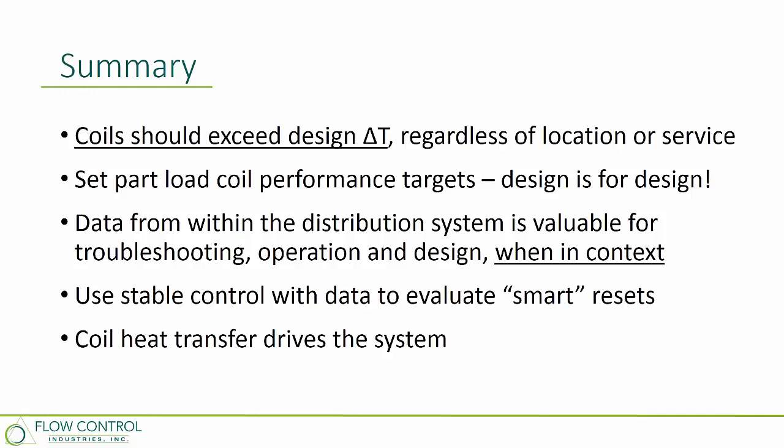But it all comes back to that coil driving that system performance and really maximizing the efficiency there so that we can provide that segue into the other complementary measures. We can take advantage of our variable frequency drives, our variable speed chillers, our resets, our total plant optimization and efficiency strategy. But all of that has to work together. And if we don't address that heat transfer at the coil first, we're never going to get that full, maximum efficiency out of the coils.